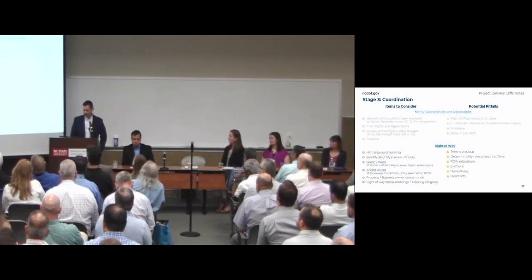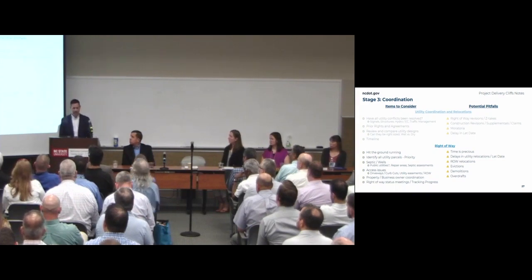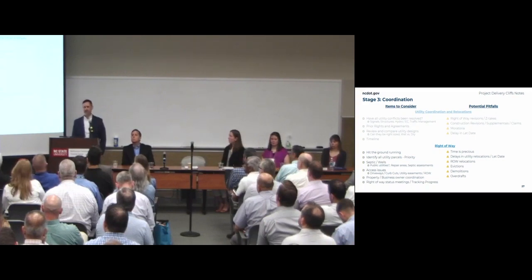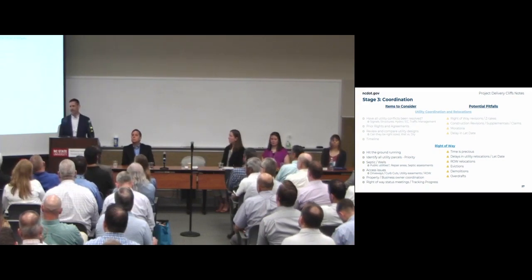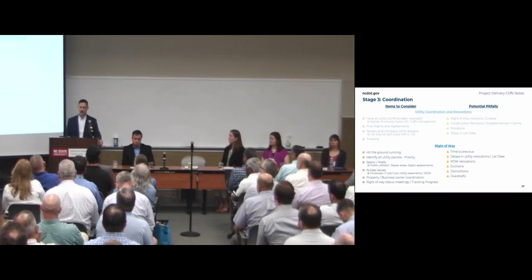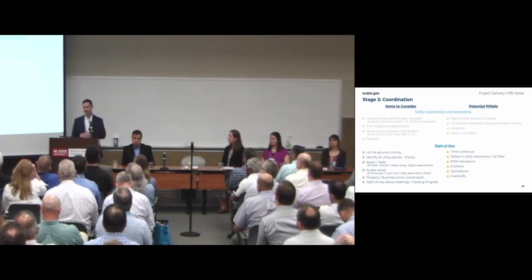And now our probably most favorite thing of all, right-of-way. I say here, hit the ground running. What do I mean? Let's try your best as you get started into right-of-way. Talk to your right-of-way firms before you authorize funds. As you're finalizing right-of-way plans, engage them early. Start talking about scoping that, get a fee in place so that once you get those funds authorized, they can start. As you all know, it can take several months to get a contract in place. So if we can have that ready, have it started, always supplement it later for more parcels, but at least they can start. You don't want to waste time.